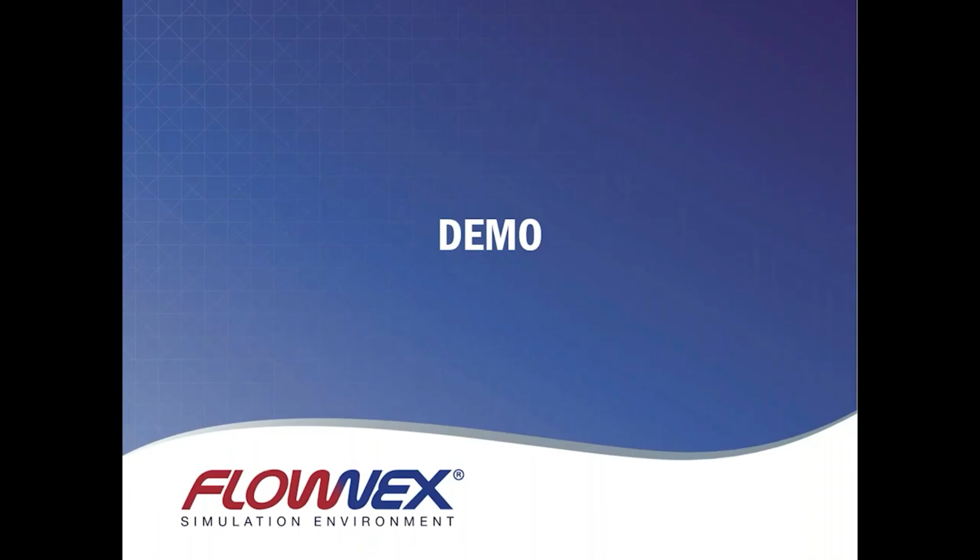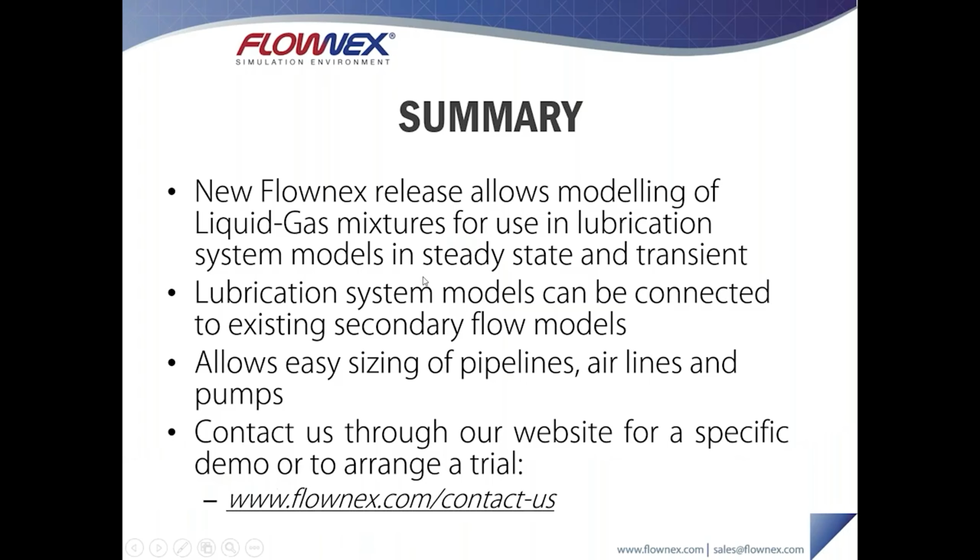Okay, so just to conclude, this new Flownex release has the ability to model liquid gas mixtures. So we can connect our liquid fluid to our gas fluid with the simple specification of a liquid and a simple specification of a gas. No requirement, no need for any complex two-phase properties. And this basically allows us to build these lubrication system models, which we can then use in steady state and